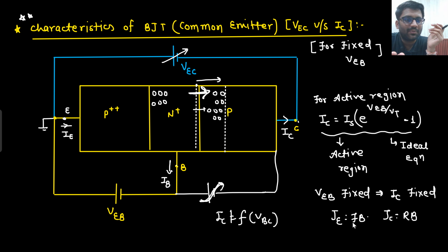People will say, why is the base more doped? Because of the fabrication. Absolutely baseless statement. If I am doping the base more, then what is happening? Depletion width is not getting extended towards the base. More and more depletion width is getting extended towards the collector. So if less depletion width is being extended towards the base, then these holes are not depending much on this electric field, and this is what I want.